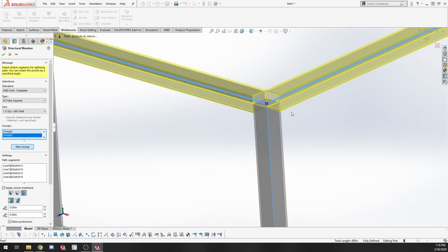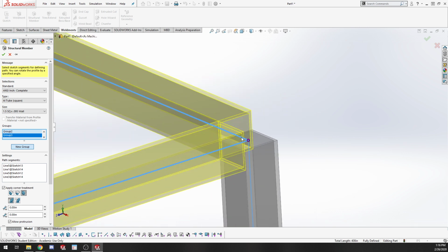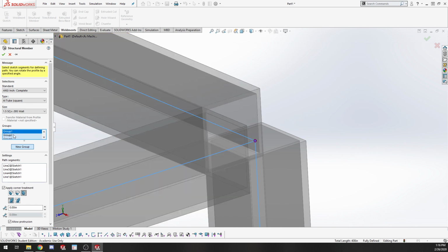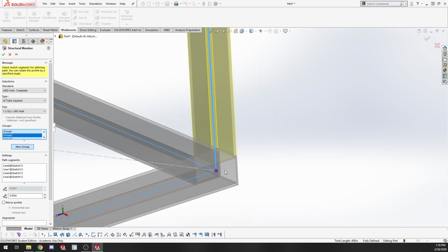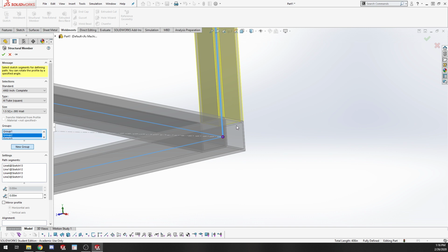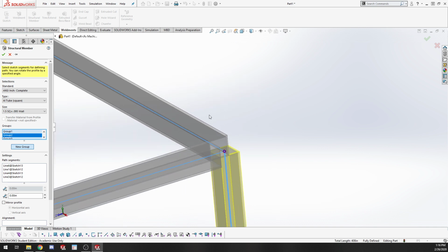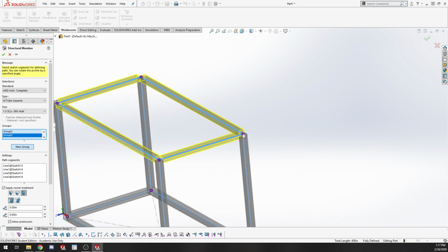All right. And one thing to note, you can see this corner here looks a little wacky. The reason is that SolidWorks evaluates these groups one after another. So it first creates this one. Then when we add in this one, you can see the corner treatments go right up to there. It's not going through it. These tubes already exist, so all the tubes that I'm adding in my group 3 are butting up against that tube as well. The nice thing is, I can go in and override it.